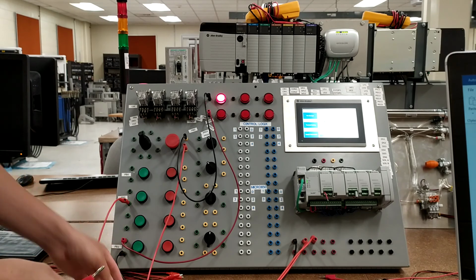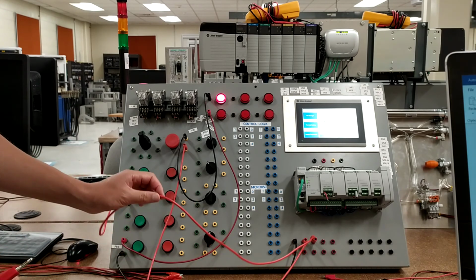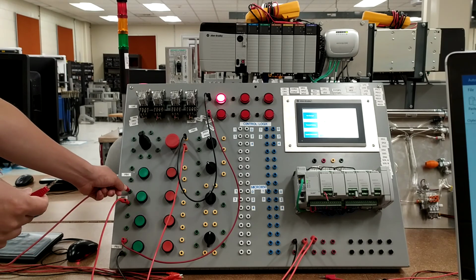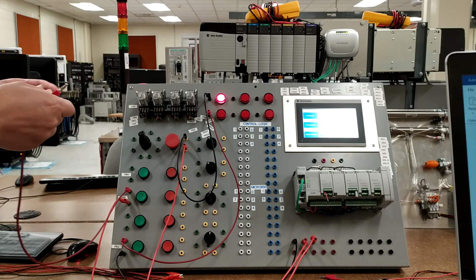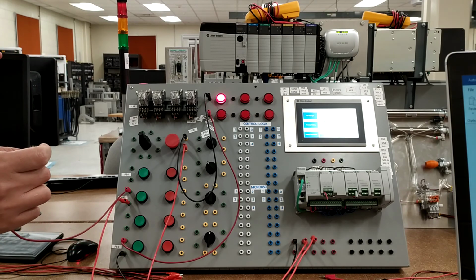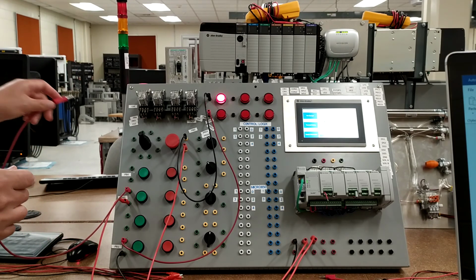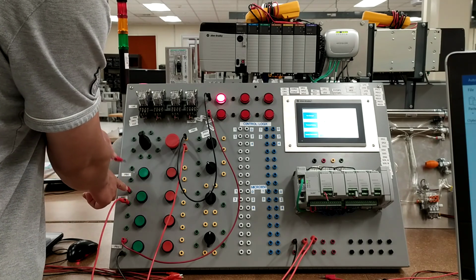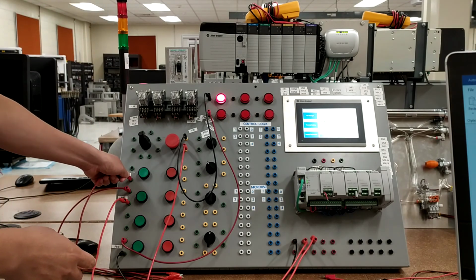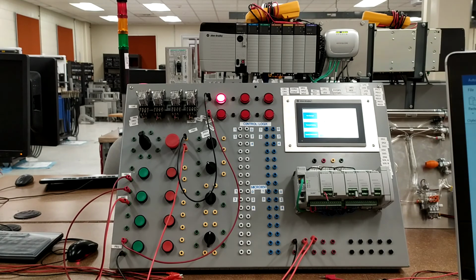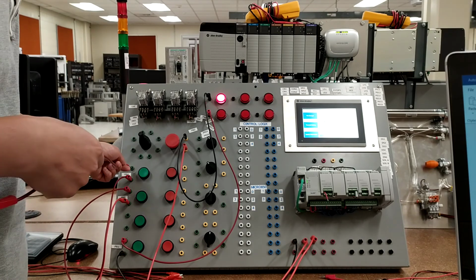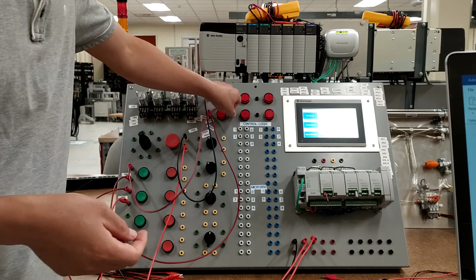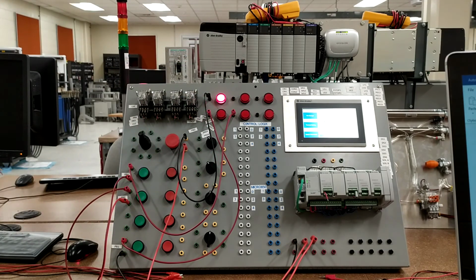After the power supply is connected to push button PB3, we wire in series. You need to remember how to wire push buttons in series. From the power we come in to PB3 and out to PB4, and PB4 comes to the pilot. Let's see the result.